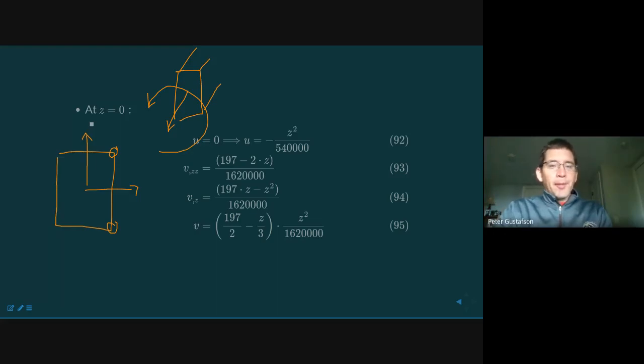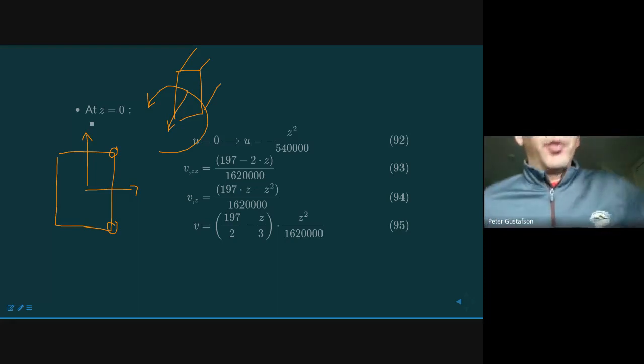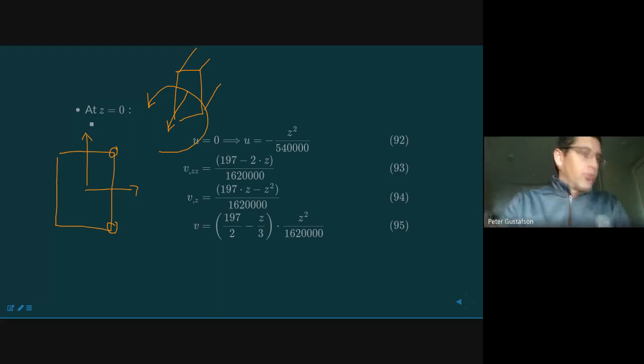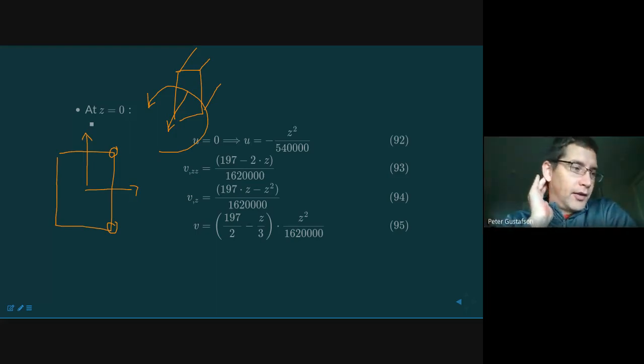It turns out it doesn't impact the stresses that we have computed, but it does impact the local shear stress at any given point within the cross section. So it doesn't change the overall resultant shear stress, that is the integration over the entirety of the area, but it does impact locally, at one given point, what the traction vector at that point is. So Amir, thanks for pointing that out. We have not addressed that issue yet, other than to say it is a torque. So great question.